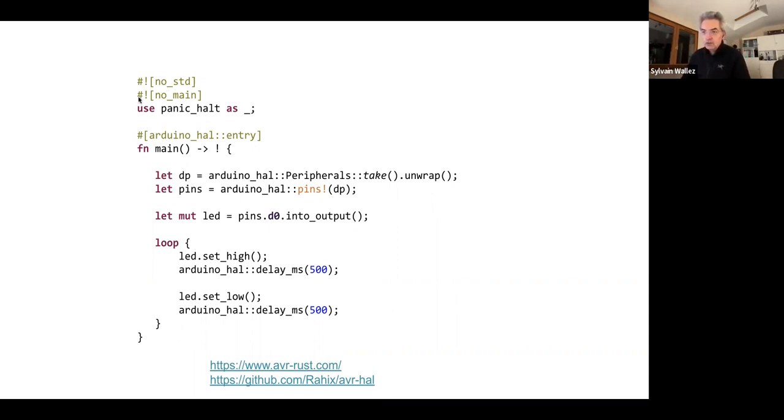And we instruct the Rust compiler that this is the case by adding this attribute here, saying our module has no main function. And this thing here is actually specific to the Arduino environment and decorates the main function with a specific name and the very tiny thing that is required for the boot process of the microcontroller to actually start the function.